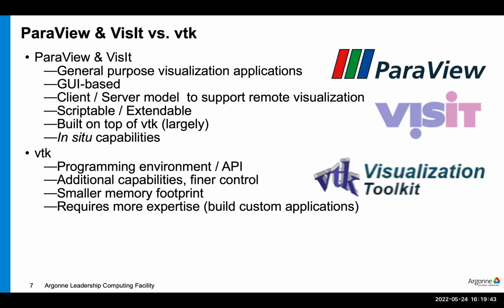So apply filters and materials and colors and such, and camera views, lighting, all that sort of basic configuration, and then you can save that as a Python script, and then run ParaView or VisIt in batch mode to go off and render animations and such in batch, so you don't have to keep the client connected.